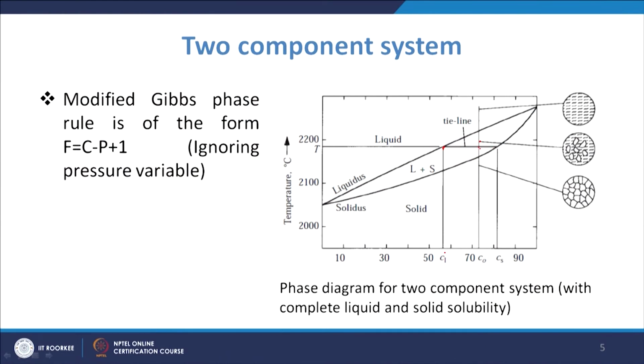So, that is being calculated with the help of the lever rule. Now, the lever rule tells that if you take this point as the fulcrum of the lever, the fraction this upon the whole will be the part of the solid, and the fraction this upon the whole will be telling you about the part of the liquid which is there.